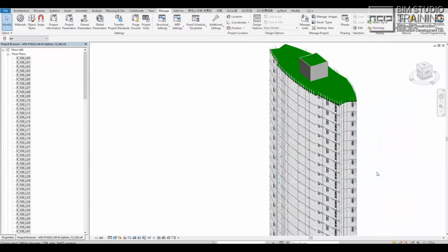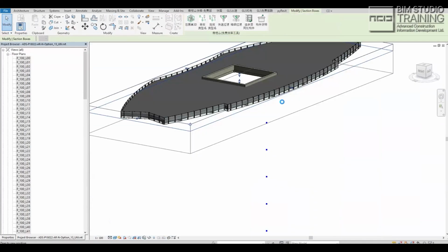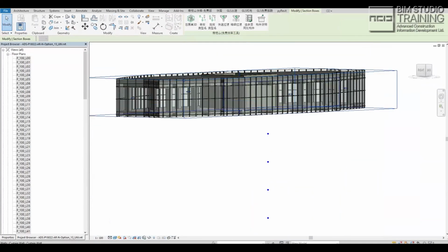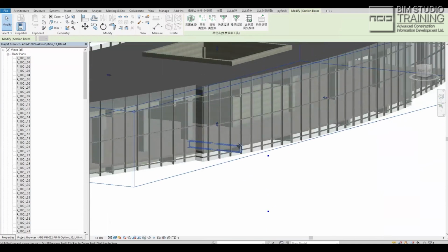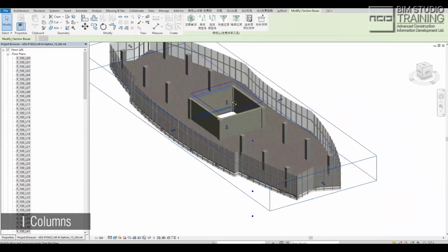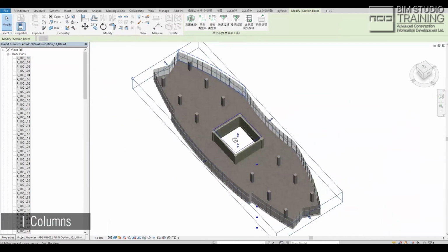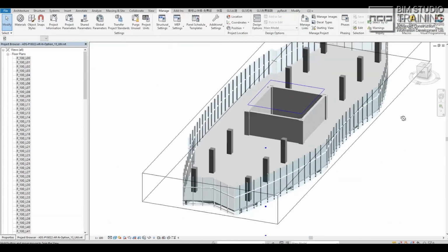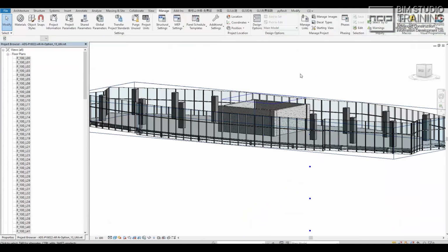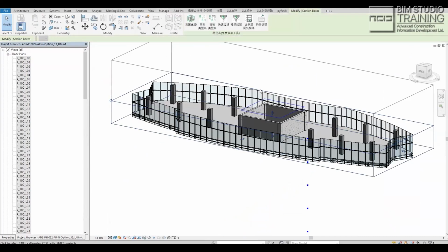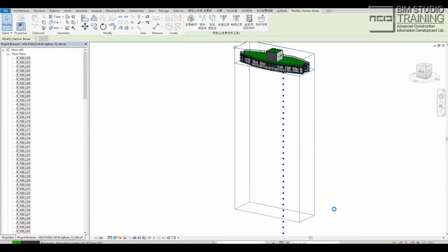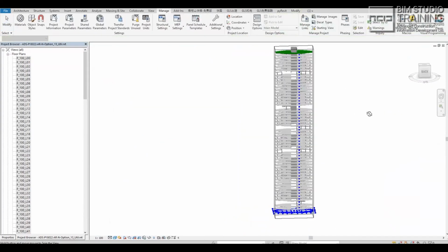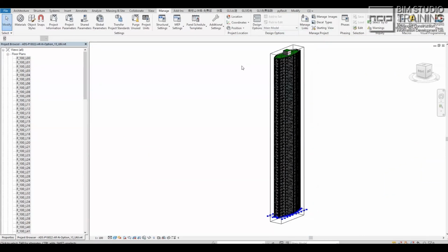We have the floor to floor height, then we know the number of stairs. So the number of steps, we know how the area is. From the area, we know what the lift core is. How many lifts we have, there are rules of thumb. From this area, we kind of know how many columns there are, and what the size of the column is. So we have a column, we have a distance, we know the size of the beam. So these are rules. We tell them the rules.